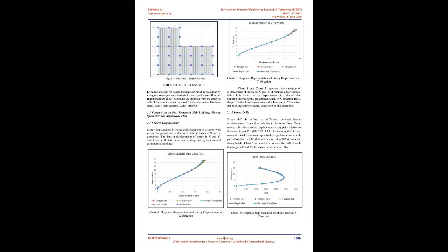E. Loads on the building. Seismic zone: Zone 2. Site type: 2. Importance factor: 1. Wind speed: 39 m/s. Terrain category: 4. Live load on terrace: 1.5 kN/m2. Live load on floors: 3 kN/m2.